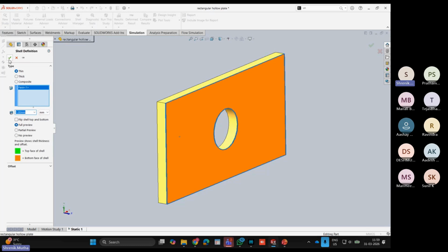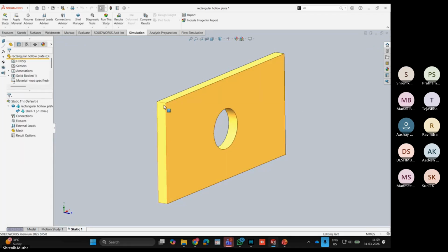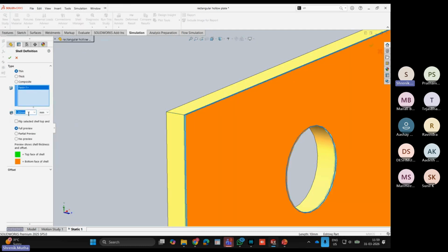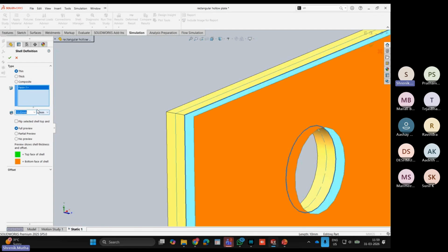We'll stick with the static simulation. Again, we're gonna cover all these parts in this series of SolidWorks Simulation. Yeah, sorry, we have to change the thickness. I'll just check its length is 10 mm. I'll just edit definition from here. Again, change it to 10 mm, say okay.